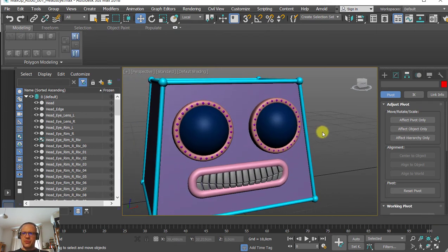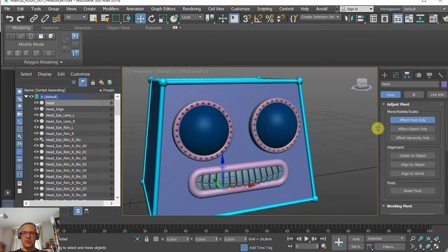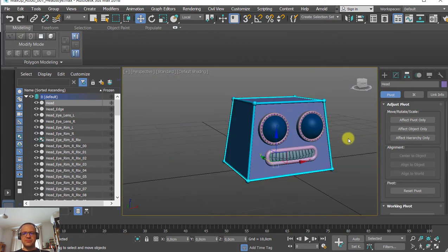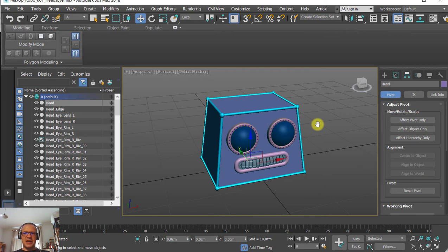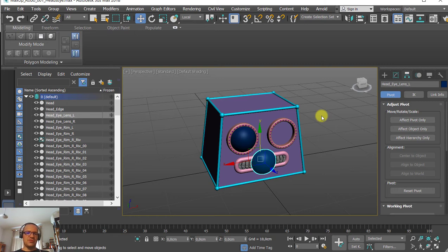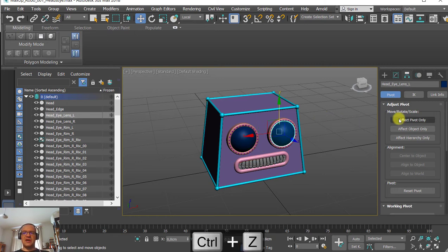Now you know what a pivot point is. Now you have a grasp on it, so that's how a pivot point should be adjusted. So when we are affecting the pivot point, anything that is selected is affected. Now you're ready to move the pivot point, and then you can click again to exit from editing. You can switch between objects, and you can align the pivot point itself. If we have a model here and we start aligning that particular model to something else, it will move the model and not the pivot point, right? So if you experience this, this is because you haven't activated the pivot point editing.